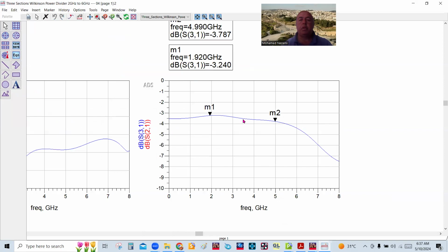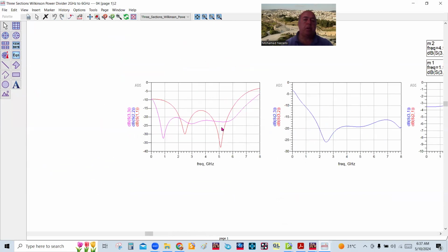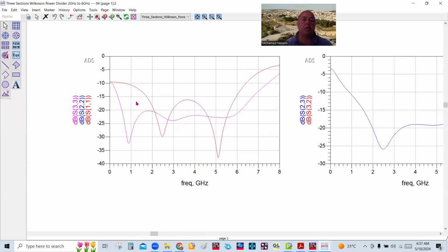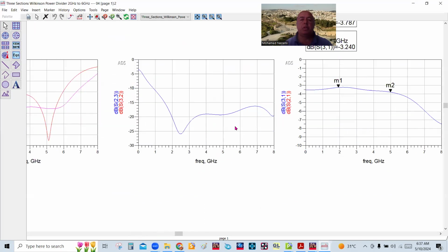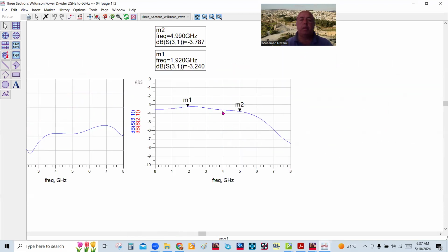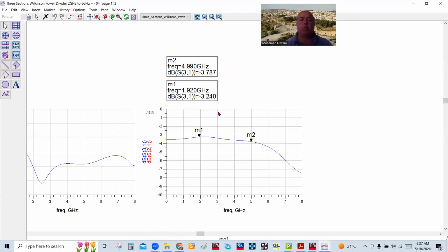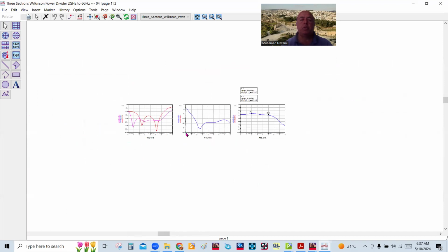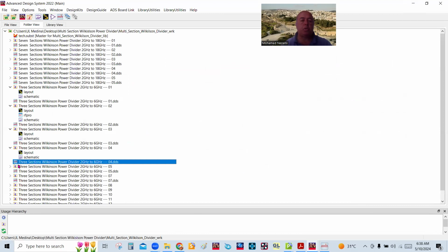You can see that first of all, the return loss is good. It's a little narrower, okay, and the isolation is worsened a little bit. It's below 15 dB, and then the ripple or the roll off is pretty high in here. So you've got more than 0.5 dB of insertion loss variation across the band in here. And that's because of the parasitics of this resistor in here.